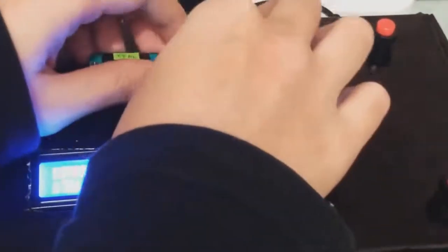So we need to secure and lock the IC chip on the ZIF socket, and then press the first switch to choose the IC and the second switch for the process. So this is the process for the IC testing, which is based on the truth table. It will start to process one by one, following the sequence of the truth table. As for the result, all the IC gates are working.